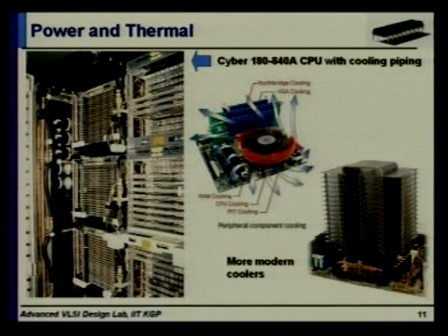To give you a glimpse of this, the picture on the left side is a Cyber computer. We used to have a Cyber computer here in IIT Kharagpur. These Cyber computers were based on ECL technology. You have heard of MOS. Have you heard of TTL? Okay, ECL is another logic family like that, like MOS, like CMOS. ECL is a very fast logic, because the switching speed is very high, but the current consumption is extremely high.